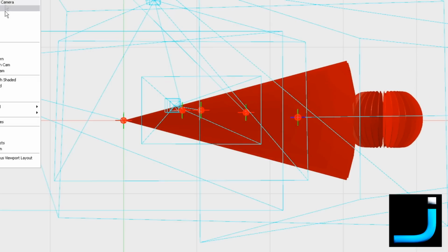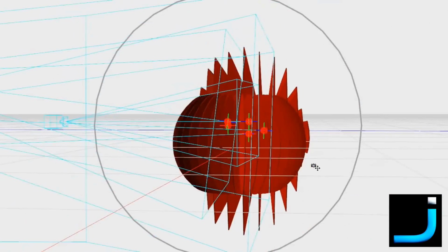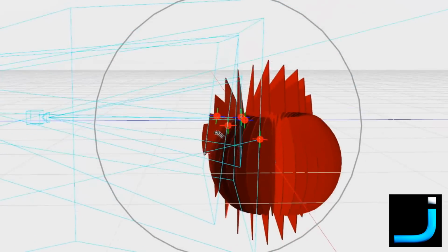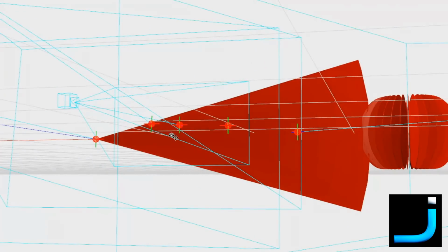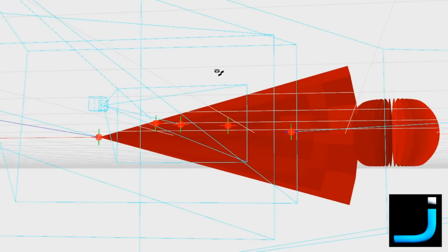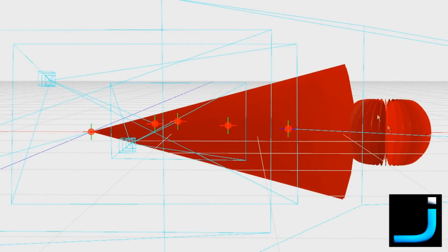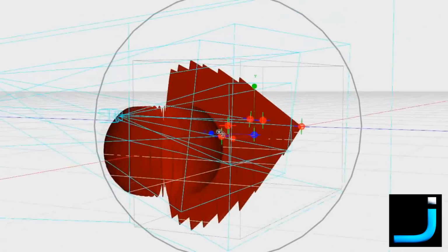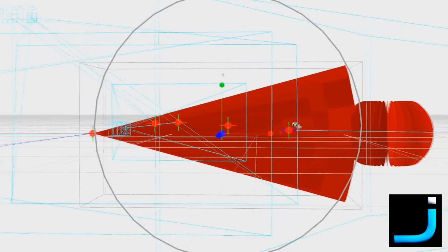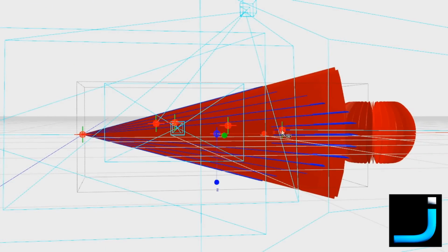We still have the same problem though, remember. We've still got the problem of the linearity of it. It's either vertically or horizontally polarized. So again, one of the ways we can get around that is to have the best of both worlds. For example, we can have our Yagi that's vertically polarized, and we can have another Yagi which is horizontally polarized right next to it.